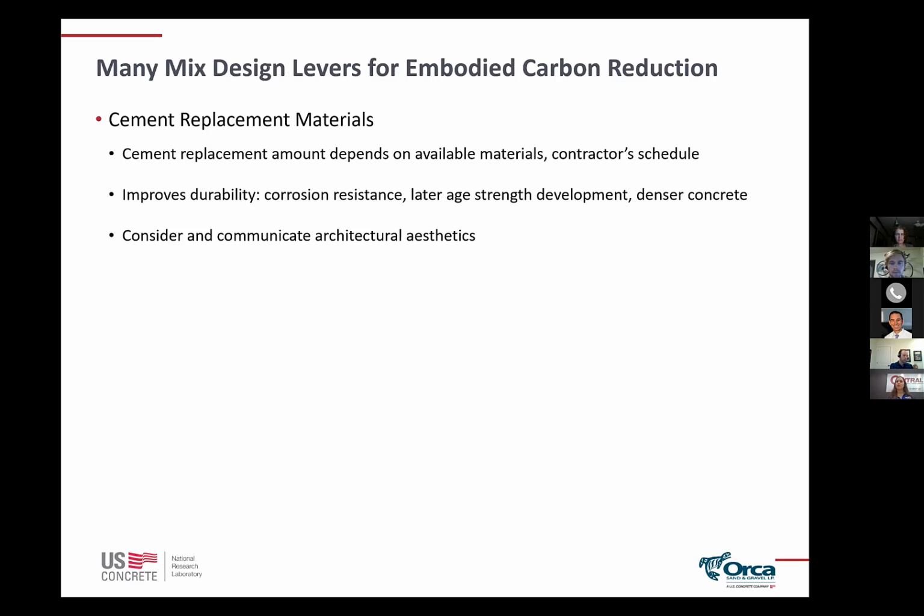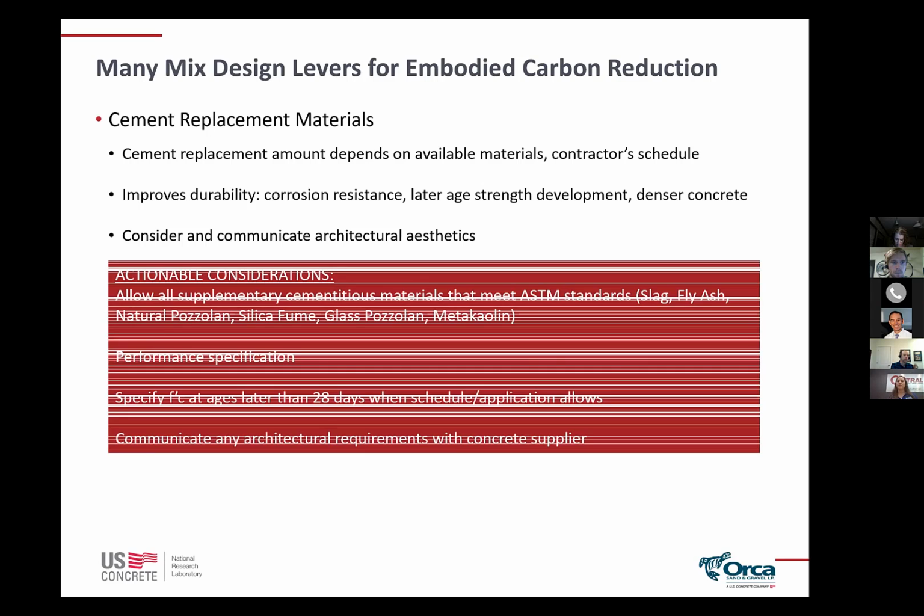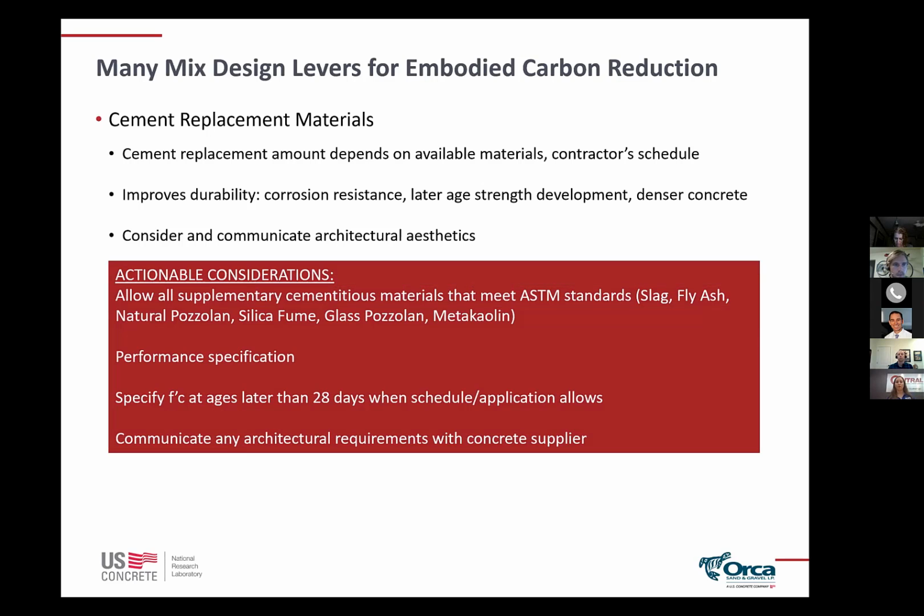With SCMs, you can usually achieve denser concrete. You're going to get strength gain that builds up at a later age, which helps contribute to the durability and strengthening of the concrete. And you're also going to get corrosion resistance with these. It's also important to consider and communicate the architectural aesthetics that you may be going through for your project.